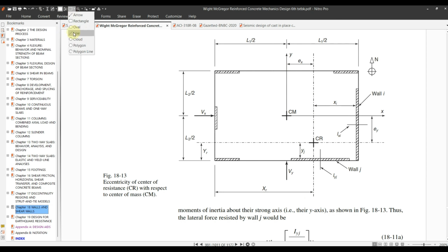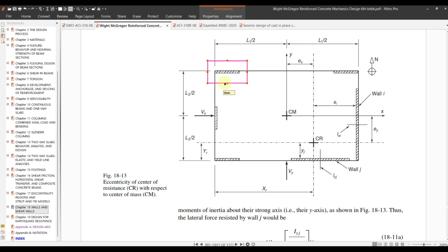So what you need to do is remove a shear wall in your model and check torsional irregularity. If, for example, at this moment there is no extreme torsional irregularity, but removing one of the shear walls at any location, for a trial basis, you have chosen to remove this shear wall, and after removing it you end up getting a torsional irregularity exceeding 1.4, the maximum drift divided by average drift greater than 1.4, then it is called the extreme torsional irregularity.